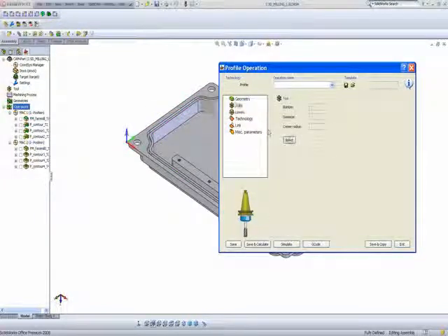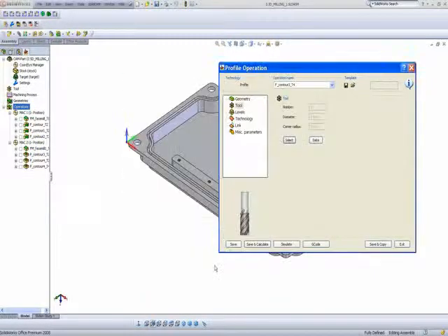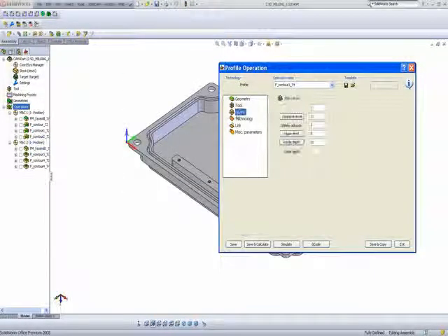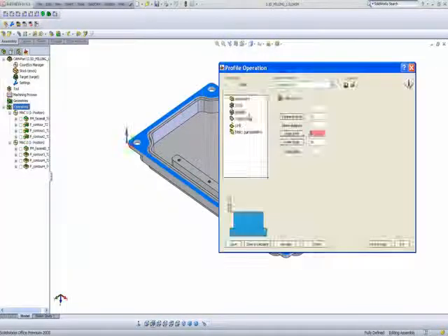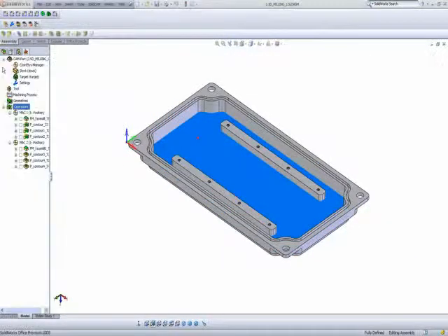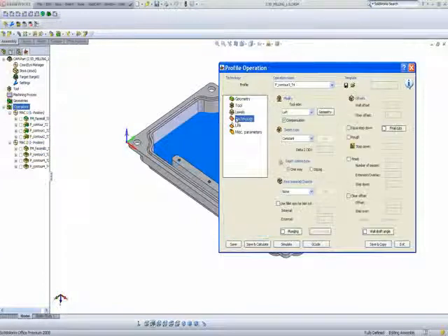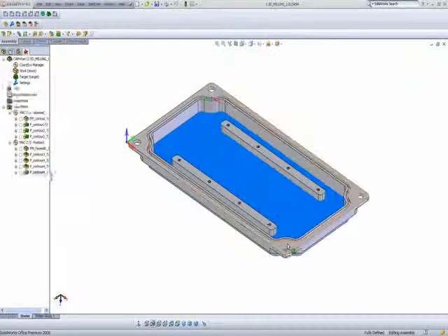The tool that I will be using will be tool number 4, my 6mm end mill. My levels will be my upper level from very top, and my profile depth will be at the very bottom. Now my technology, I'll be working on finish only, and in my link area I have my lead in of arc, and I'll have the same thing with my lead out.